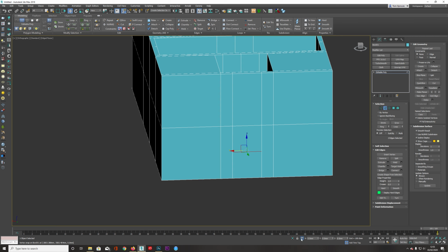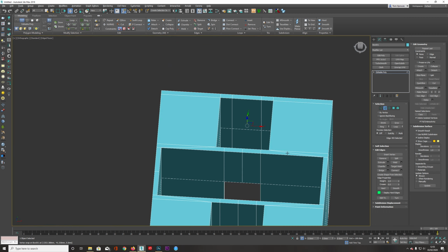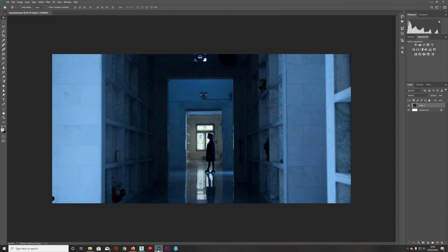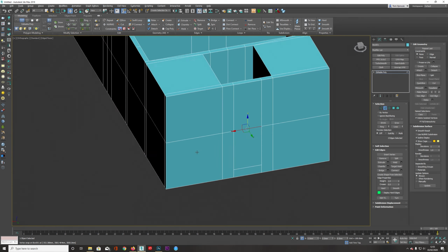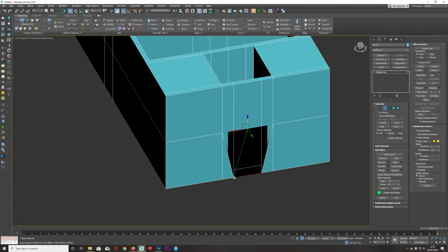So this can come down, just snap that down to the bottom, and then move this up. This is on the Z-axis because I'm not front on. Just come up 500. And then here, I just want this, and that one, and yeah, let's come back down to 220. So to get this into the right place, I'm just going to bring this all the way down to the bottom.